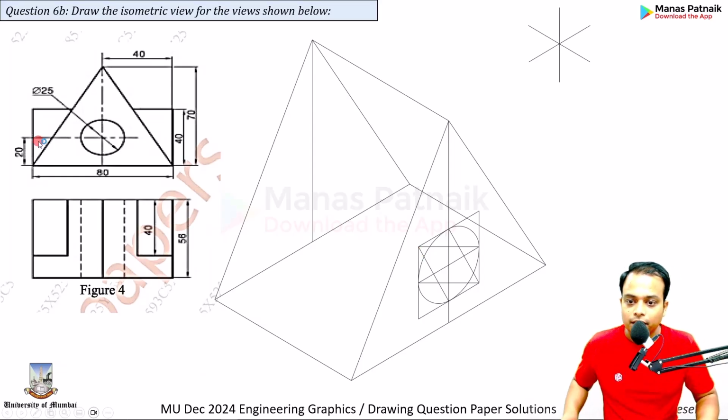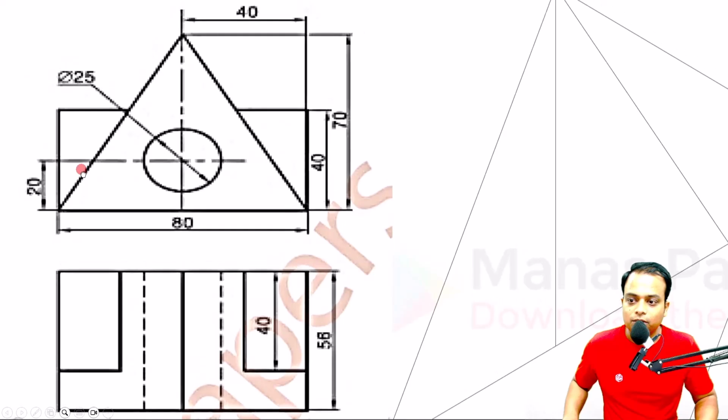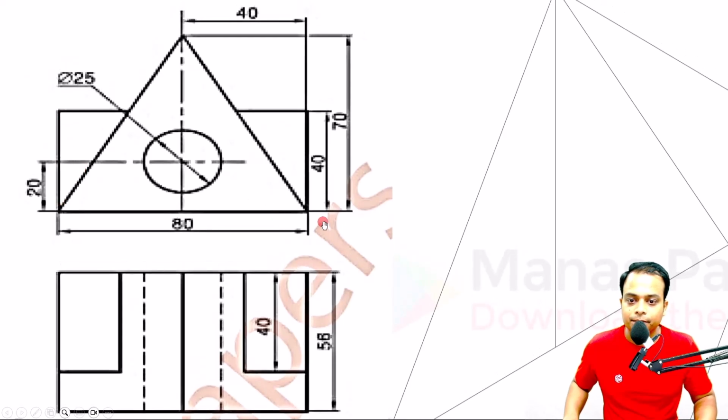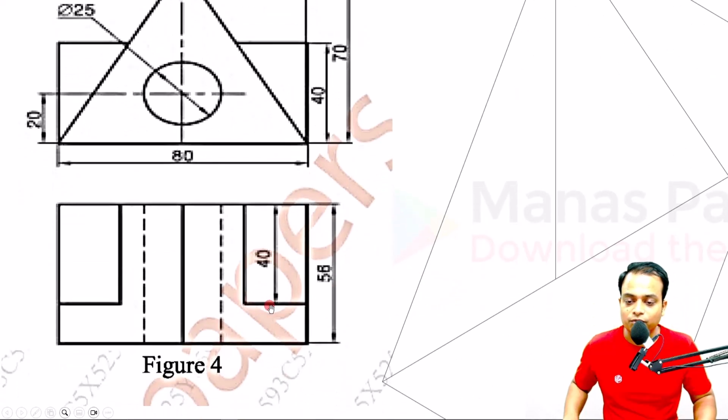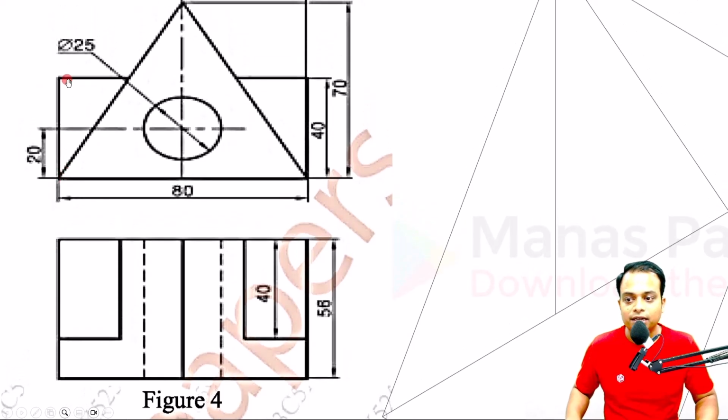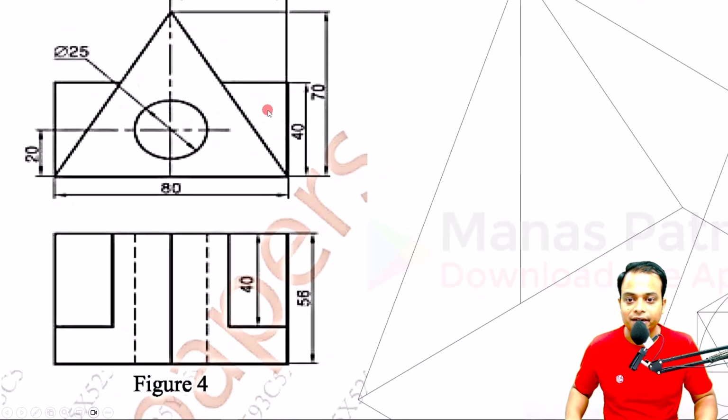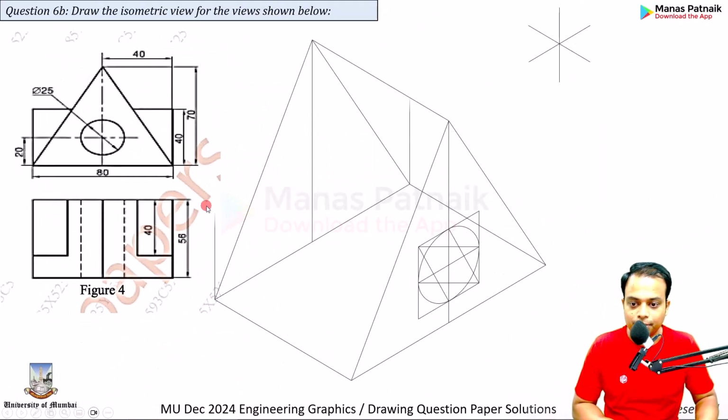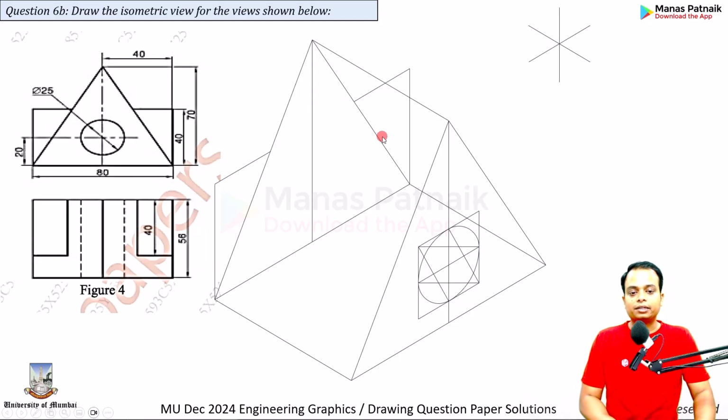Now, if you take a look, this height is 40. Okay, and how far is this profile? Only for 40 millimeters. So first of all, let me make this right at the back, 40 up, and then go this way until it intersects this inclined line. 40 up from both the sides, and then to the right, to the left, until it intersects these two inclined lines.